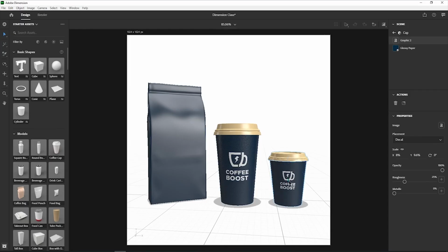And by the way, you can simply drag this gizmo so you can change the position of the logo. So right now I'm pretty much just eyeballing the logo. Maybe rotate it a little. But you can always use this properties panel to adjust it accurately.